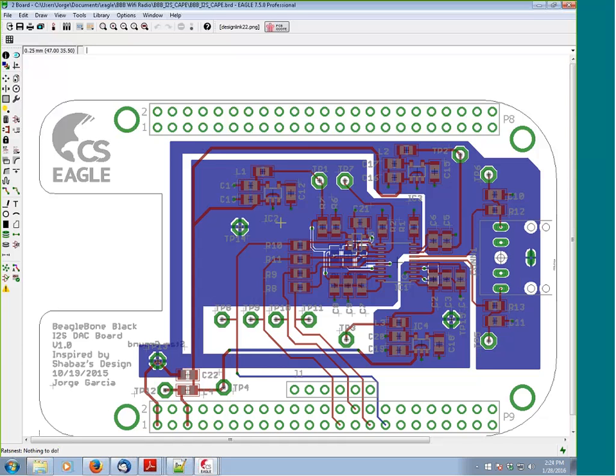A couple of key points about doing this type of grounding arrangement. First and foremost, the 3 planes only meet at one point, which is this area over here. They're meeting right here. They don't meet anywhere else within their boundaries.